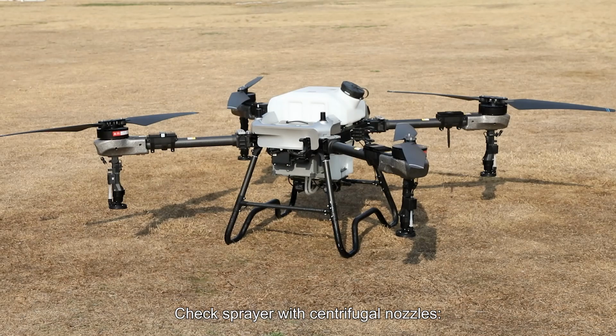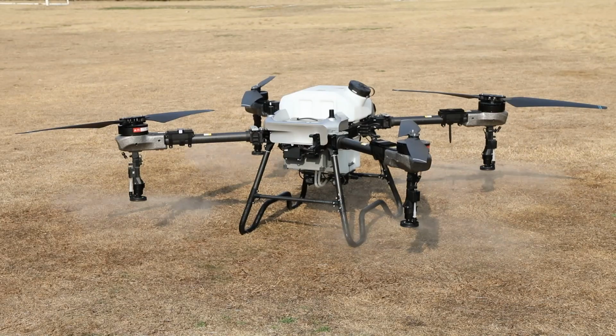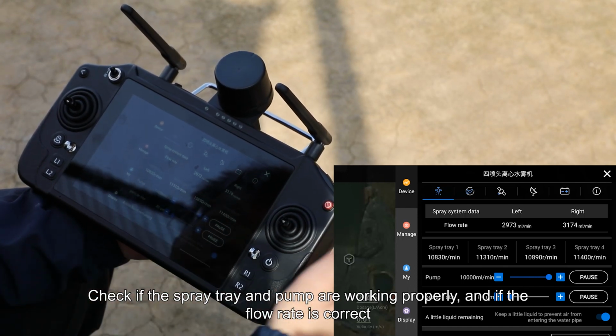Check sprayer with centrifugal nozzles. Click Settings. Click the Start button on the right of the particle size setting and click the Start button on the right of the pump setting. Check if the spray tray and pump are working properly and if the flow rate is correct.